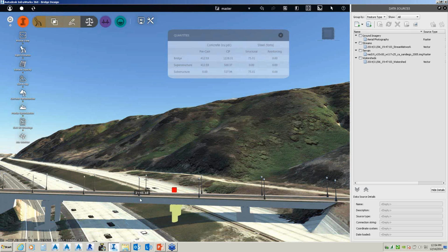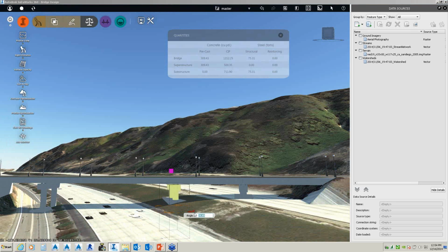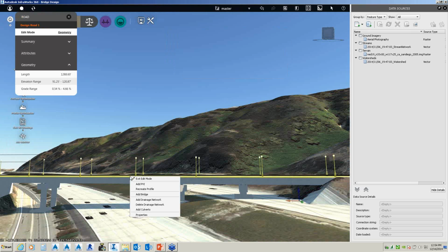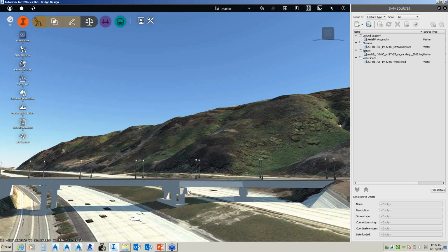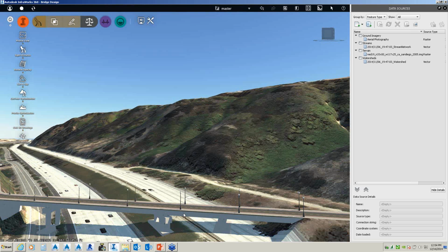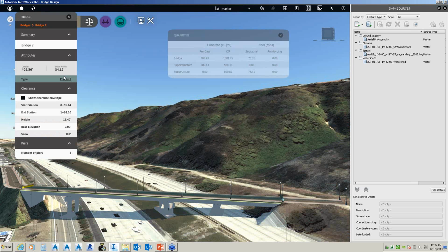So I changed the location there. And then you can see I have some small little arrows here. We'll just rotate that a little bit. Clearly, there are still issues with my girders here. So one of the things we want to be able to do also, if I right click, let me hit escape. Let me zoom out a little bit. So if I pick that girder there, I'm going to change this now to steel plate.